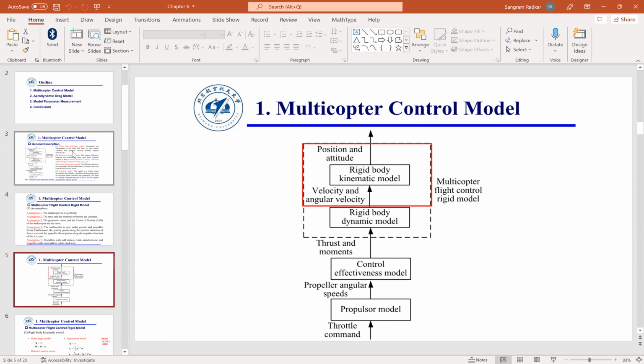The kinematic model for all the airplanes is the same. And that kinematic model is used to find out the orientation and position of the airplane. So there is something called an inertial measurement unit, which has a 3-axis accelerometer, 3-axis gyroscope, and a 3-axis magnetometer. Sometimes you have GPS. And you have the same thing in your phones. If you look at your IMU app on your iPhone or Android, you would see some sort of IMU app that will tell you orientation, position, potentially velocities of your phone. So that is the first model.